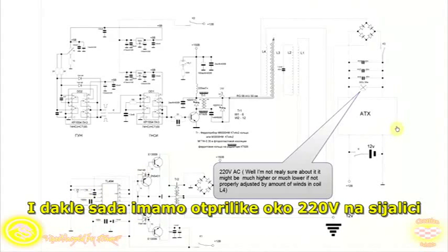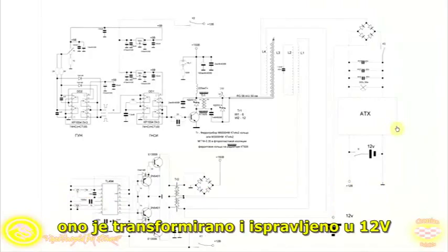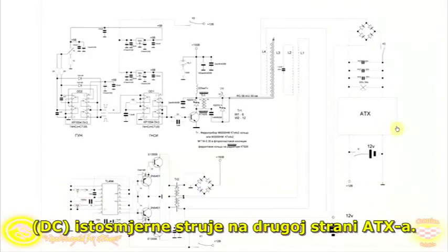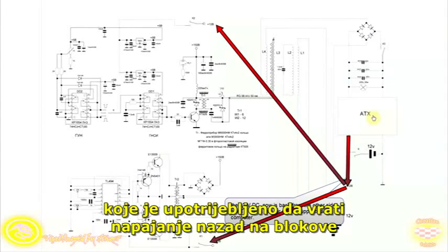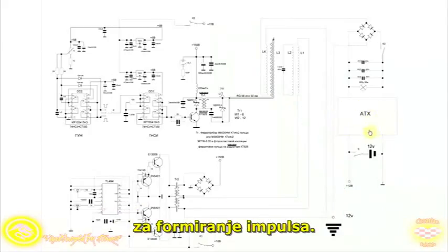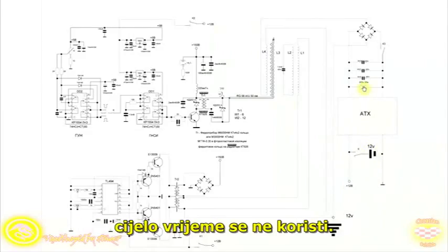And now, since we have approximately 220 volts on the light bulb, we have a 220 volts on the input of ATX, which is the regular power supply from the computer, and by that it is being transformed and rectified to the 12 volt DC from the other side of ATX. So now we have our 12 volts from the other side of regular computer power supply that will be used to power back our pulse forming blocks. Our switch K and the battery will remain unused all the time.